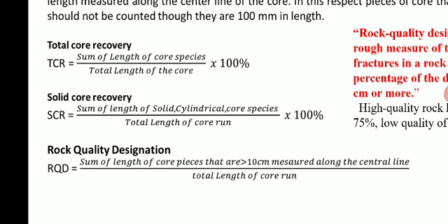That means from that core, how much is the recovery. Then what does solid core recovery stand for? The sum of the lengths of solid cylindrical core pieces divided by the total length of the core run.